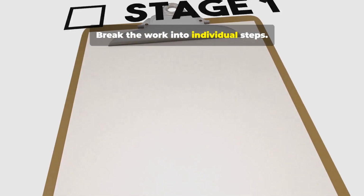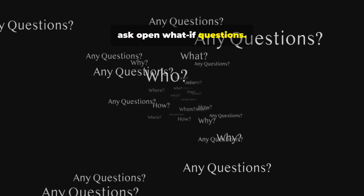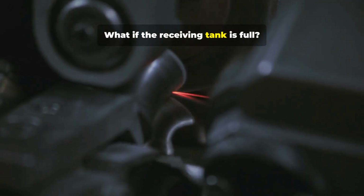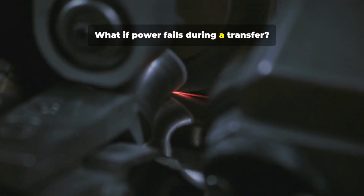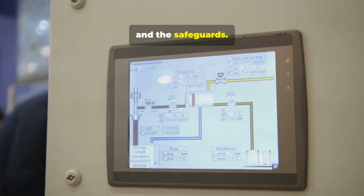Break the work into individual steps. For each step, ask open what-if questions. There are no bad questions. What if the hose ruptures? What if the receiving tank is full? What if power fails during a transfer? Record each question, the consequences, and the safeguards.